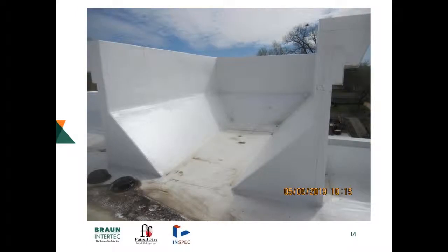Some of these areas of parapets where you have the kickbacks in order to support some of these taller parapets for architectural detailing are also areas where air can come in through those cavities up through the walls and then also diffuse out through the roofing system.